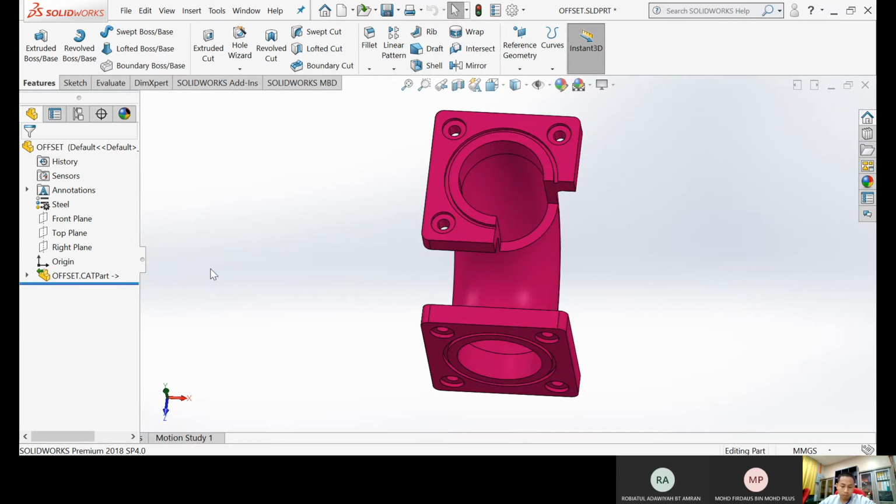For part 10, multi-body operation, using the combine feature with the subtract option, the body to combine disappears as it becomes absorbed in the feature. To create a copy of the body, the move or copy feature will be used. In this part, a holder for the camera needs to be sketched by adding some geometry to the part. There are parts that need to be split and combined in this multi-body operation.